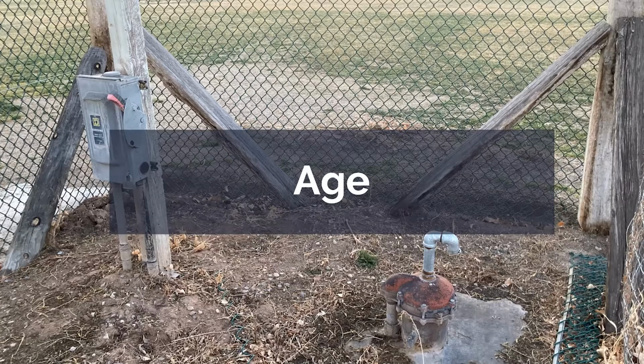And as I said, age is a factor. It's not the only one, although particularly in smaller systems, we see that becomes the default factor for pipe replacement. We recently did a pipe break analysis on a system in the Midwest. They had pipe dating back to the 1930s, and it turns out that the actual worst pipe in their system was from the 1950s, followed by pipe from the 1970s, and then pipe from the 1930s. So just keep that in mind. Age is a factor, but it's one of many.